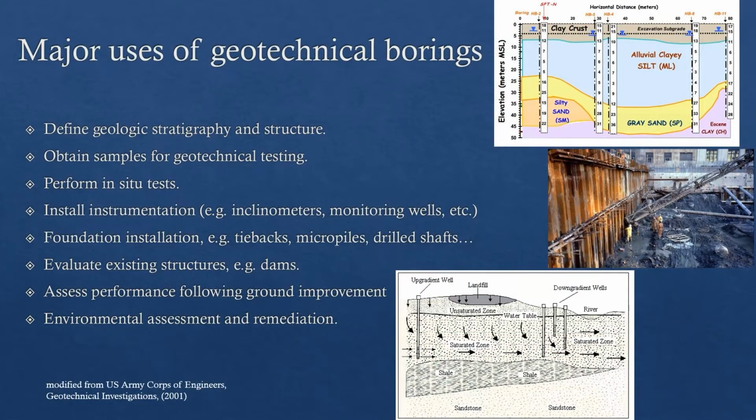So major uses of geotechnical boring, and I know most of you know this, but we want to define the geologic stratigraphy and the structure of the subsurface, whether it's in soils or in rock. We want to get some samples for geotechnical testing. We want to perform some in-situ tests. So for instance, SPT, right? We drill a borehole, we get to the depth that we want to do the SPT, and then we do it there. Installing of instrumentation, whether it's inclinometers or monitoring wells, foundation installation, tiebacks, micropiles, drilled shafts.